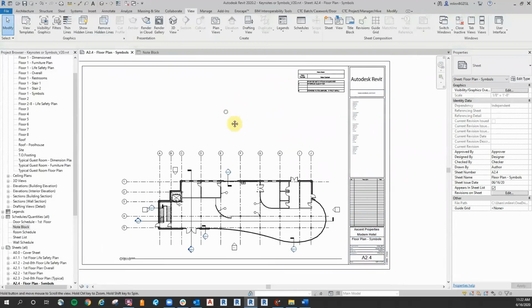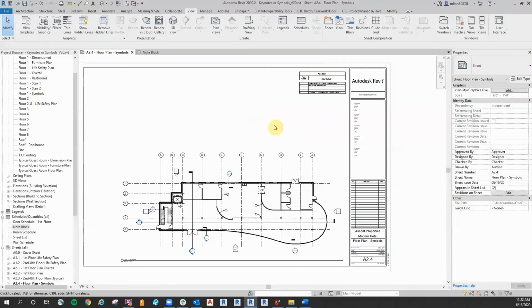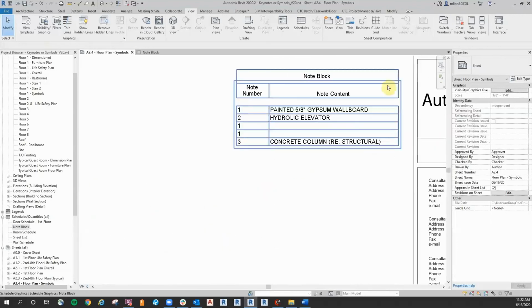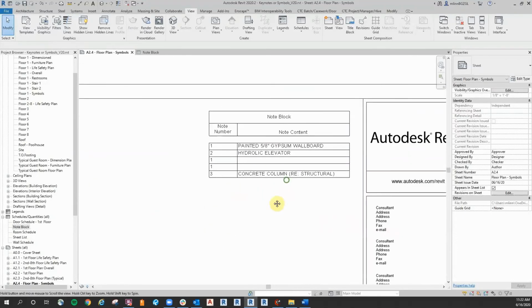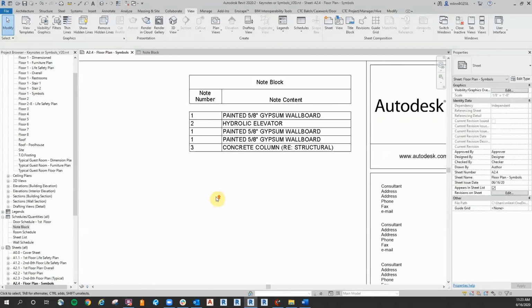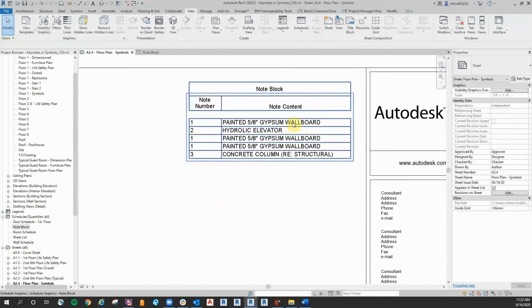Again, that's not a real clean look, is it, for your legend? You don't want it. We want all the ones to be the same thing, right? And we don't want it listed 3 times either. So we can come in here. First thing I'm going to do, I'm going to copy this value, this chipboard. I'm going to copy it to all of them, the number 1s first. Okay, so now at least they all have values.